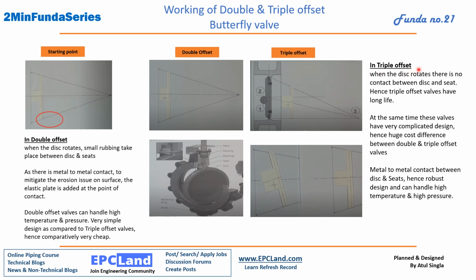What is happening in triple offset? When the disc rotates, there is no contact between disc and seat, hence triple offset valves have long life. We have discussed there is no contact, so there is a very robust design, which helps to have long life. At the same time, these valves have a very complicated design, hence a huge cost difference between double and triple offset valves. Metal to metal contact between disc and seat, hence robust design that can handle high temperature and high pressure.